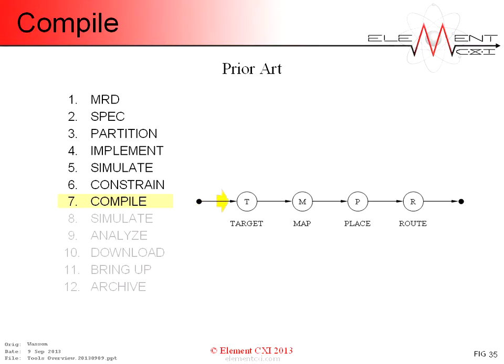Originally, this was a straight shot beginning to end, with min-cut mapping, simulated annealing placement, and shortest path routing iterations. Once a netlist was converted, the mapper was stuck with the operator conversions. Once a design was mapped, the placer was stuck with the mapping aggregations. And once the netlist was placed, the router was stuck with the component locations. Later tools added minor placement tweaks with rip-up and retry feedback between route and place, and some results could also be enhanced with rip-up mapping feedback between place and map.